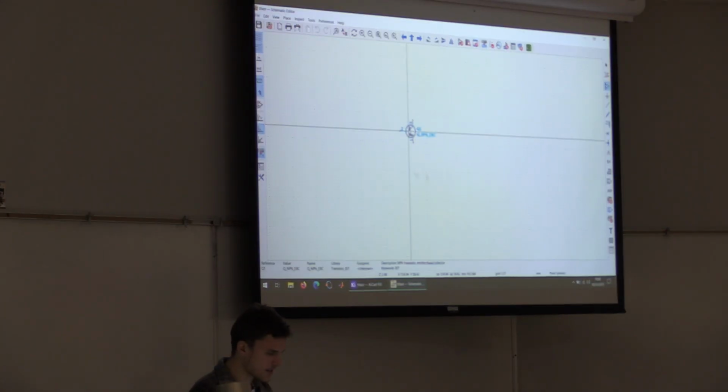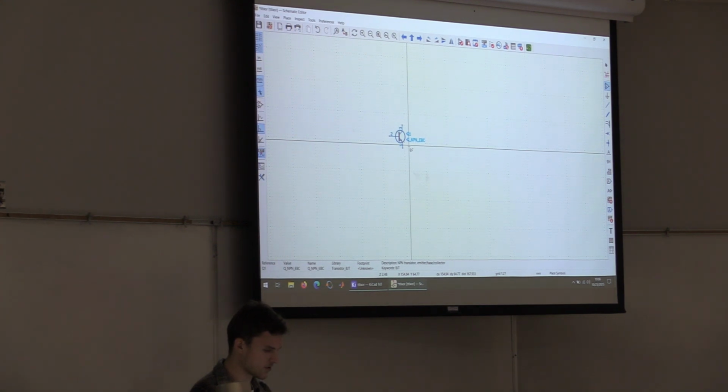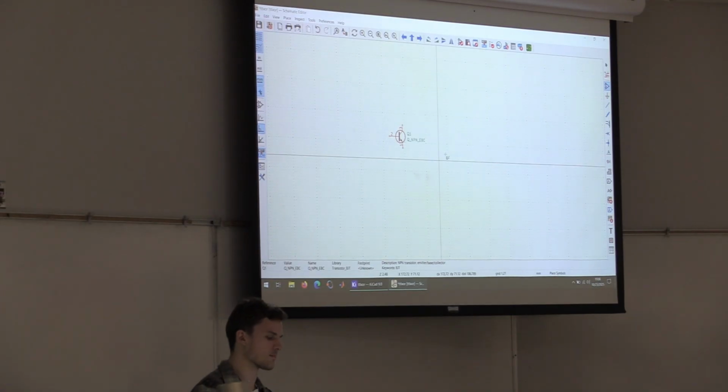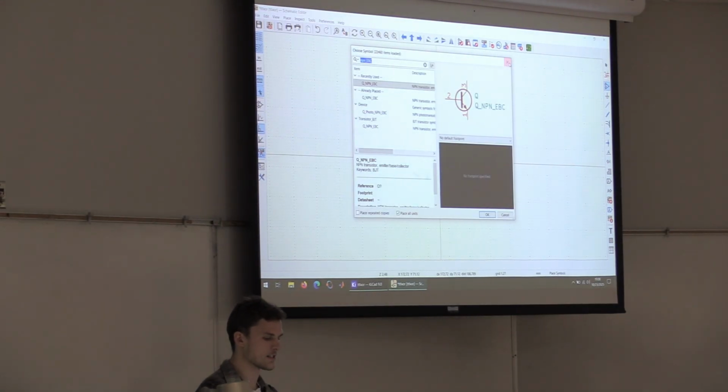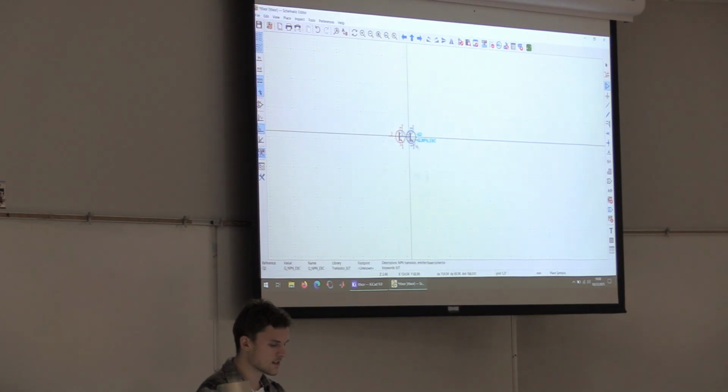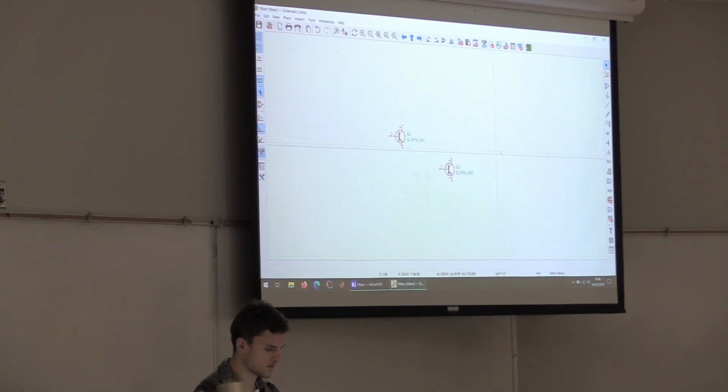And since our schematic has 3, we're going to place 1. I'm just going to hit Control C. If you don't hit escape, it'll think you want to place another symbol. So, boom, and then I'll paste the last one. I'll just throw them on.